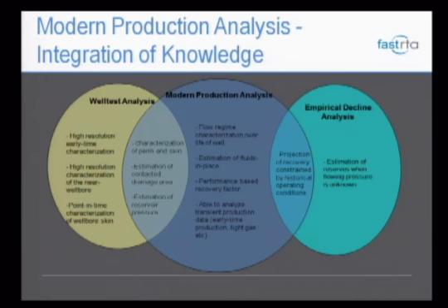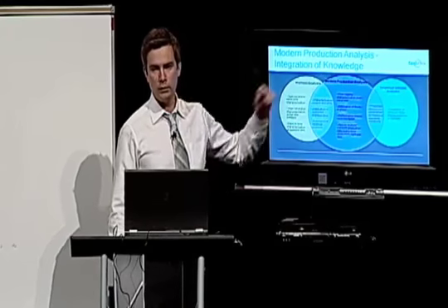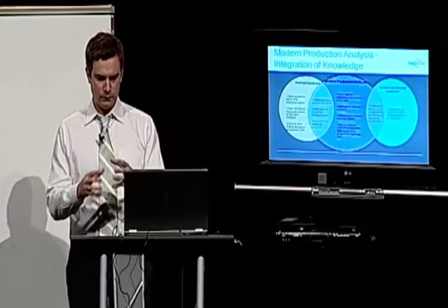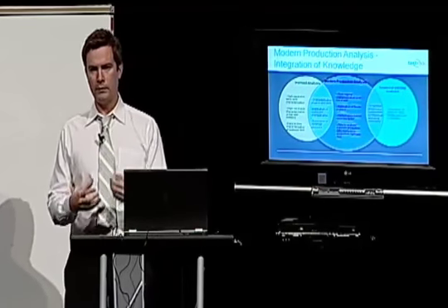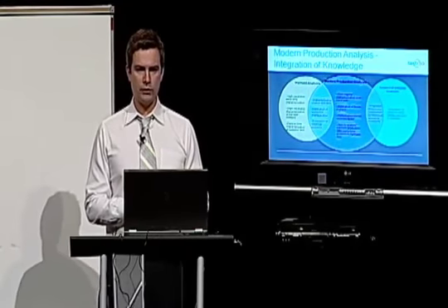Where this really starts to come together nicely is where we have permanent gauges in place that will measure high frequency pressure data. So when there happens to be a plant turnaround or something and the well is shut in, we get a free buildup that we can analyze. When the well is flowing normally, we analyze the drawdown as production analysis. So that really, if you think about it, marries the two concepts of production analysis and pressure transient analysis.